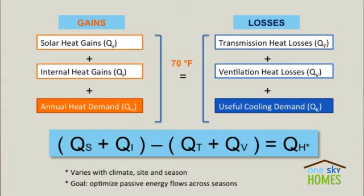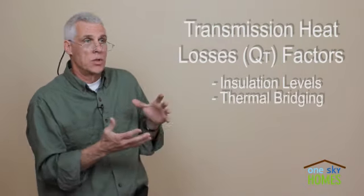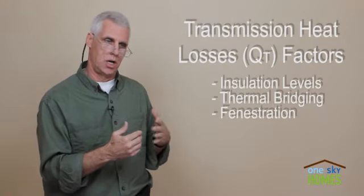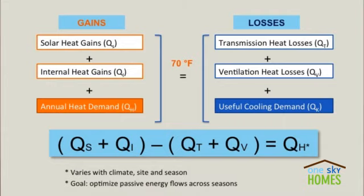On the loss side, QT plus QV, QT is transmission losses. So here's where we're designing insulation levels, and we're avoiding thermal bridging in our building. And we're designing for windows and doors, what we call fenestration. Okay, what's the quality of these windows? How many are they? How big are they? Because they have certain characteristics with respect to heat flow. Okay, so this is QT, and this determines, when we put this together, what our transmission losses are passively.